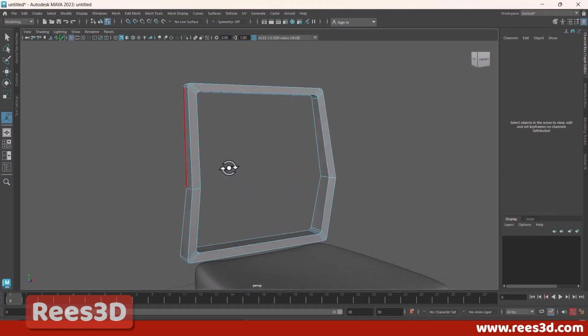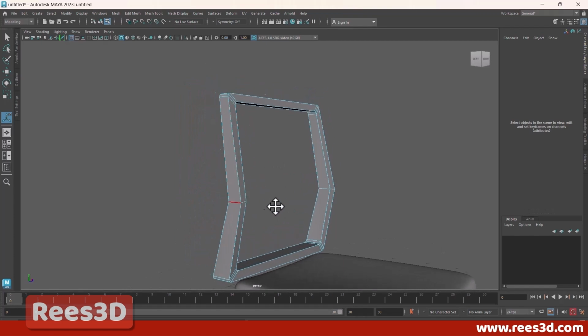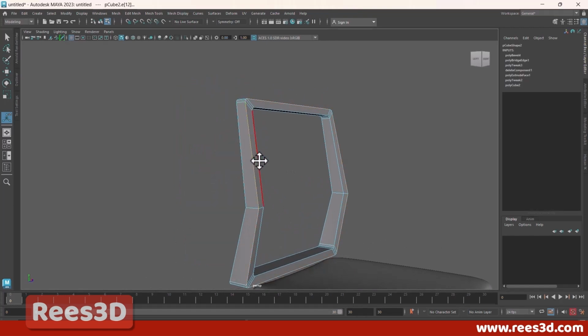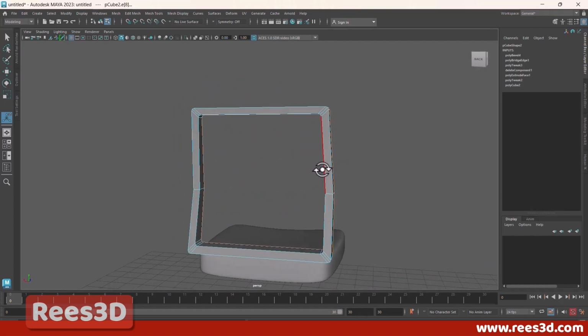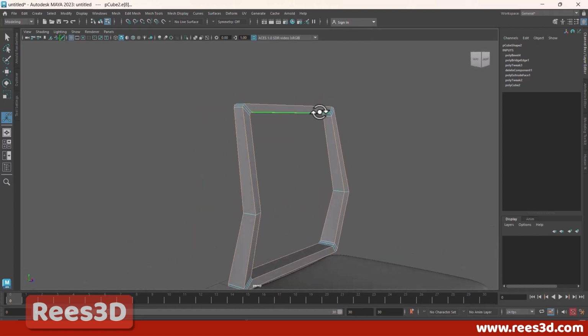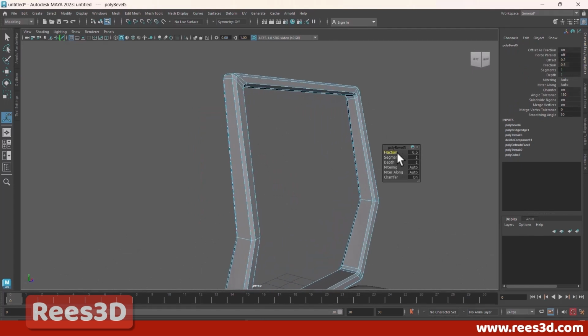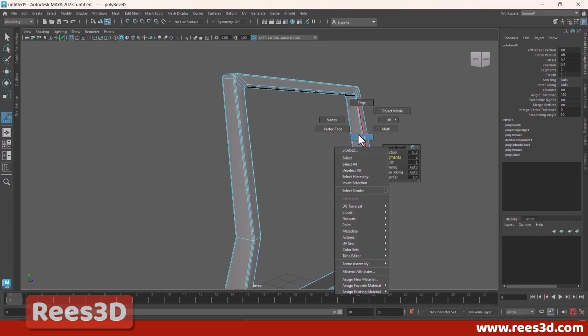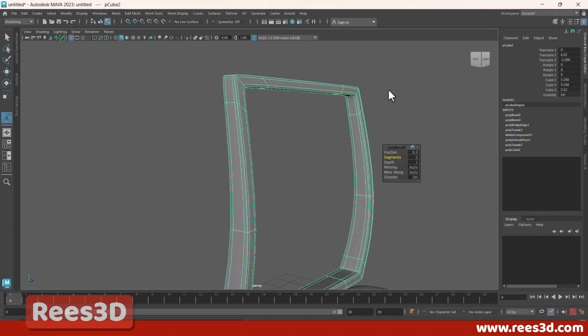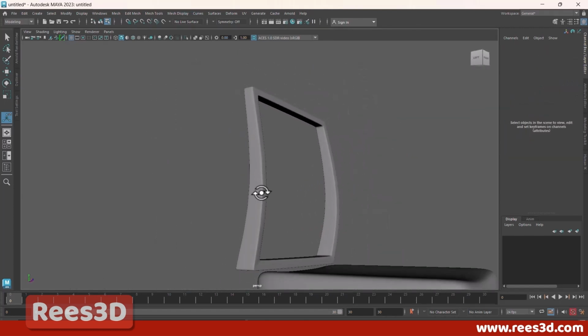All right, so I should do the same thing for these vertical shapes. So I'll just double click on this one, double click on this one, double click on this one, and double click on this one. So I get all of them, and I'll give bevel edge here, and I think that's fine. 0.5 should be fine, or maybe 0.2, 0.3, I guess. Yes, we'll give 1 segment there. I'll press 3 now. Looks perfectly good.